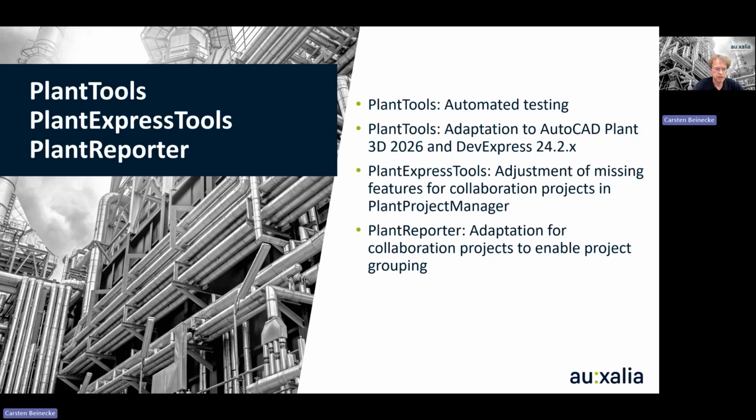That's often important for owner-operators who don't have their whole plant in one project. They typically use multiple projects. Or if you have one big project and you want to split it up for whatever reason, then you can group projects and create reports over multiple Plant 3D projects.